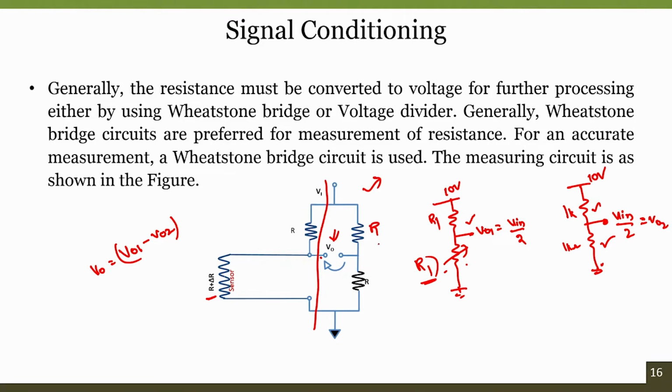Right. So, this is the advantage of going with the resistive Wheatstone split circuit. Another advantage is, when we have two different sensors, one with R plus delta R and the other with R minus delta R configuration, or with the same R plus delta R. Suppose this is also another sensor, R plus delta R_T, but it is only for measuring the temperature. Whereas this one is R plus delta R, which changes with respect to the physical measurement, and this one is for the temperature compensation.